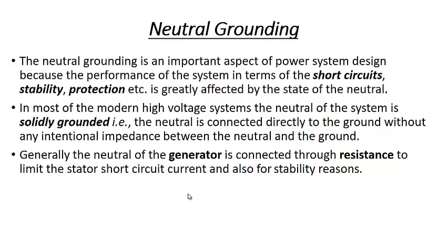This was about cables. Now let us move to the neutral grounding. One of the important aspects of the power system is the neutral grounding. When we design a power system, based on this, we can analyze the performance of the short circuit. We can analyze the performance of stability, and we have a lot of analysis in case of protection. And when we do that, this neutral grounding has a great role to play in these topics, that is short circuit analysis, stability analysis, and power system protection.